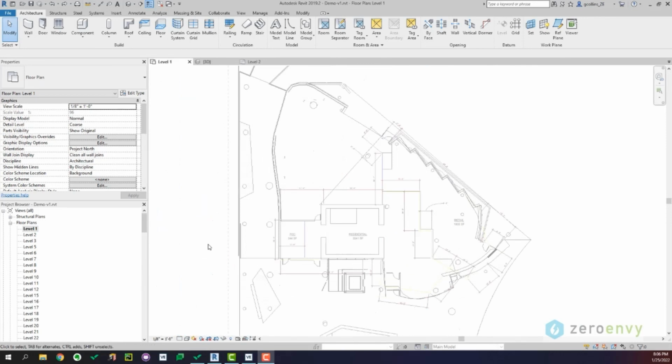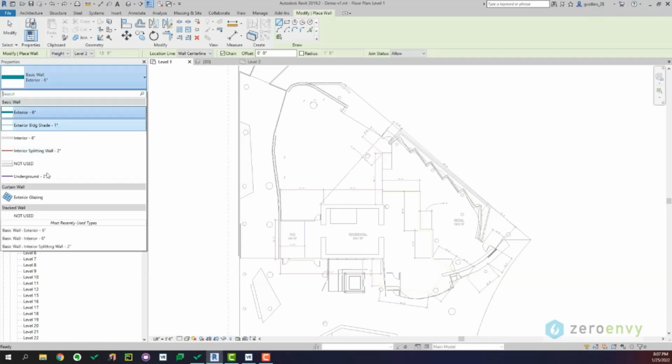One thing I forgot to mention is that we have a Revit template in which we have created a bunch of envelope components. Every time we start a new model, we start from the template and turn that into a project. And then we can just pick the components from there and start creating the model. If you go to wall category, you can see we have created a few wall types here, and we have also color coded them so they can stand out once you turn the color on.